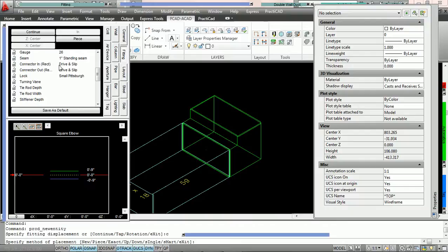Once again, it's always width by depth. So the drive is on the width of the elbow. And if you take a look, this is the cheek. The cheek is the width for elbows in Practicum. So the cheek is carrying, or the width is carrying, the drive. And it needs to, because the drive would be right here. We always want the drive on the depth in this particular tutorial.